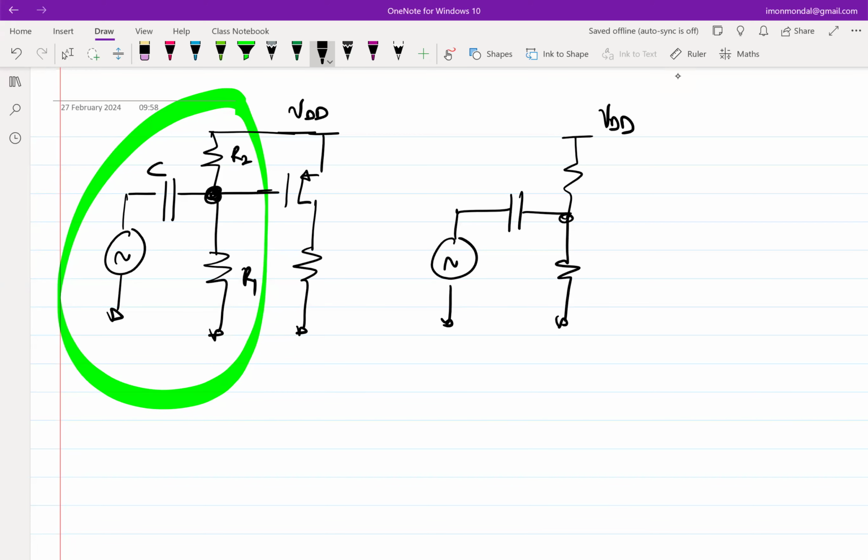And when we are talking about what is happening to an AC input, essentially what we are saying is what is happening when only this input, let's say Vp sine omega naught t, is applied, and we are not bothered about what is happening to the other input. The other input in this case means whatever the voltage supply is, because this is a linear network, I can deal with each of these inputs, the DC VDD and Vp sine omega naught t, separately. So we use that to our advantage.